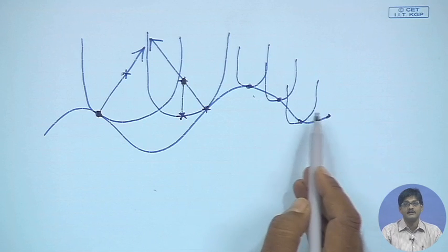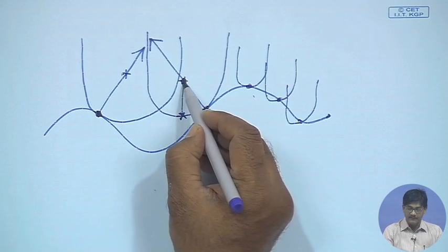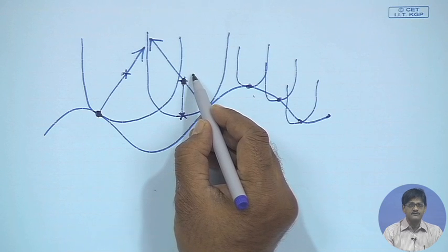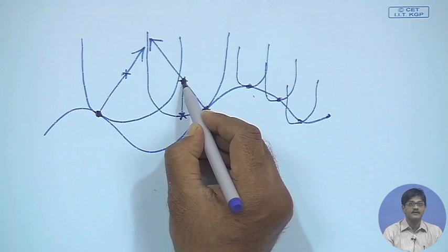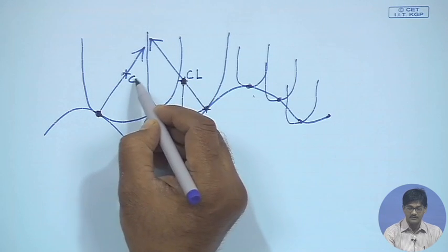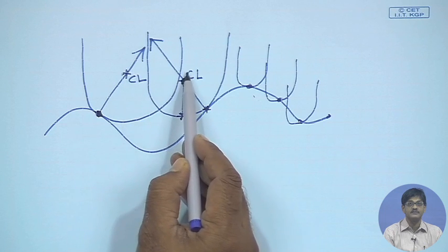Part of them are inside, it should be in the touching condition. So, we define certain points on the cutter which are specific points, say the center of the spherical portion, and then we say it is a cutter location point, which locates the cutter exactly in space.